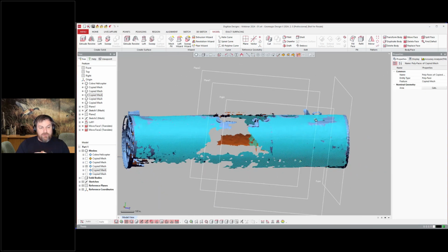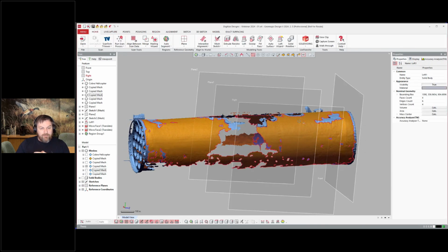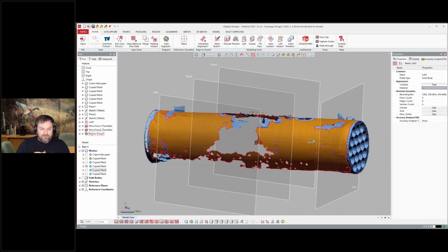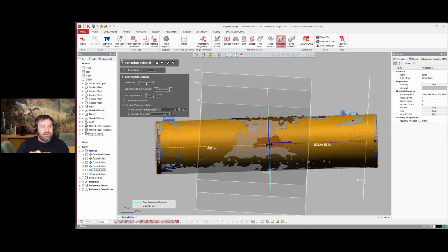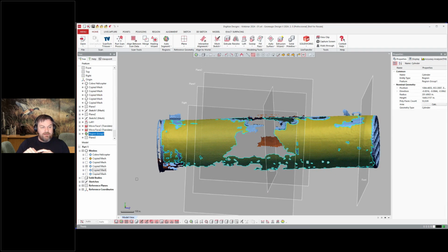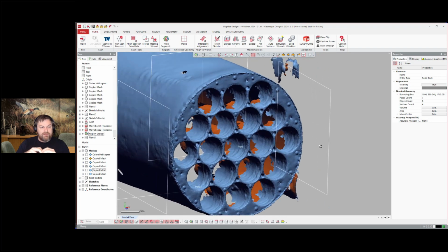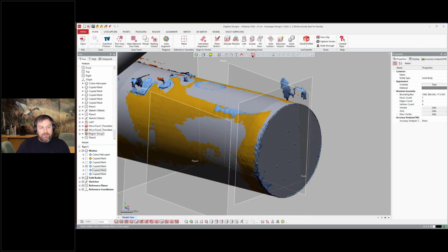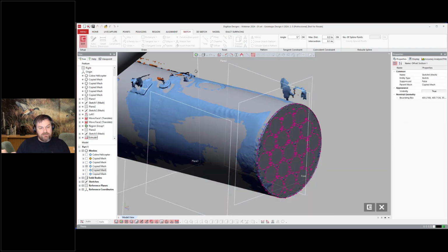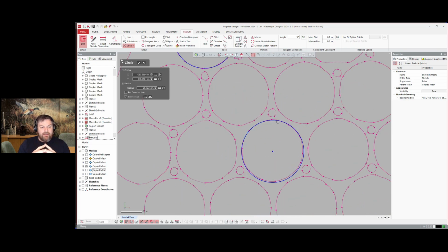Now what we're doing here with this component is I am selecting those polygons with a tool there, and then I'm creating a region there. And then instead of modeling this manually, I'm telling it to go ahead and use what we call a wizard there. So I said create an extrusion from this area. And what it did is I grabbed that region, said create extrusion, and it just automatically drew the sketch and created it for me.